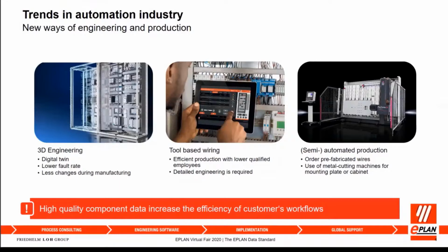mounting plates and cabinets. And these are all processes that are very efficient, but these are also processes that need more and more component-related data, because to go these ways, the user does not only need the logical representation of parts, they also need a 3D representation, so a 3D file. They need connection point patterns. They need drilling patterns for these components. So this topic of high quality component data is more and more important for our users when choosing the components.